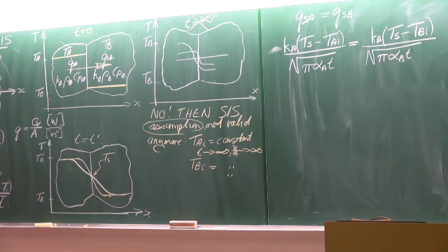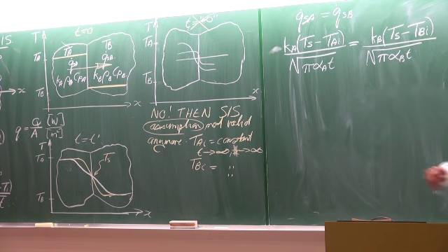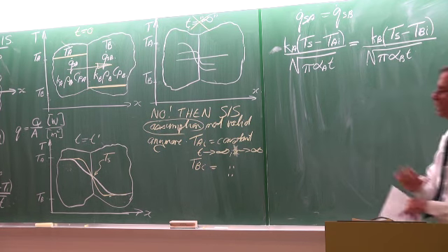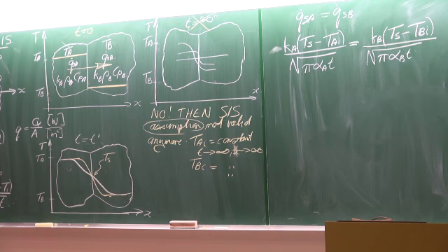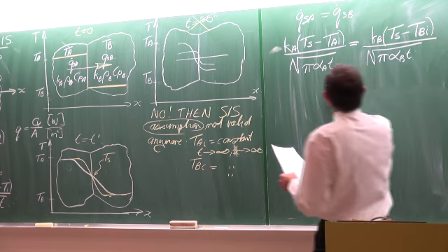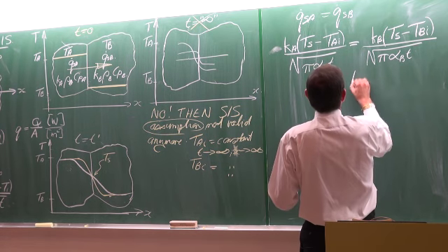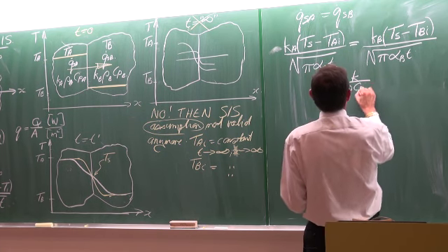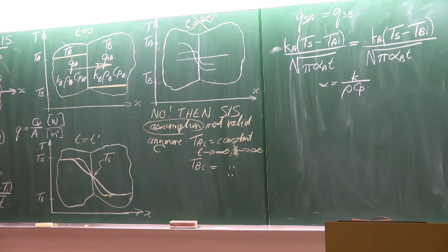So K multiplied by the surface temperature minus the initial temperature of B, divided by the square root of pi multiplied by alpha, the diffusivity, multiplied by time, must be equal to 0. This term must be equal to that term, the two heat fluxes. And remember, alpha is the diffusivity, which is K divided by rho Cp, if you can't remember what it is. Right. So if we now look at these two equations, are you happy with them?